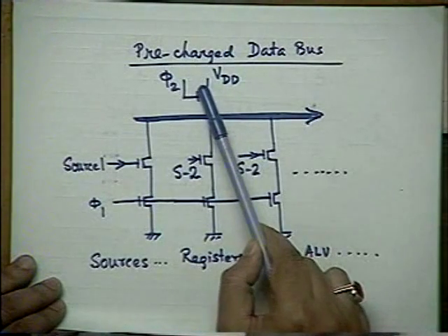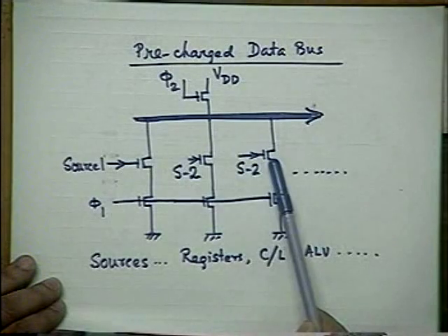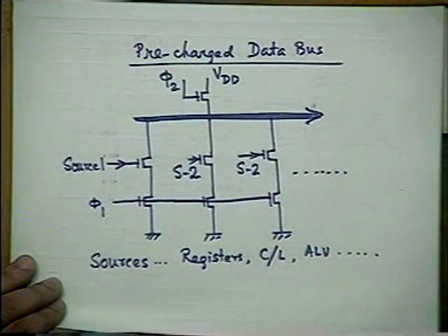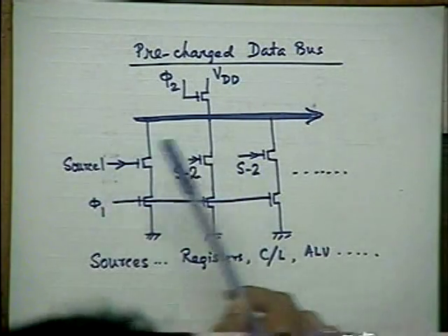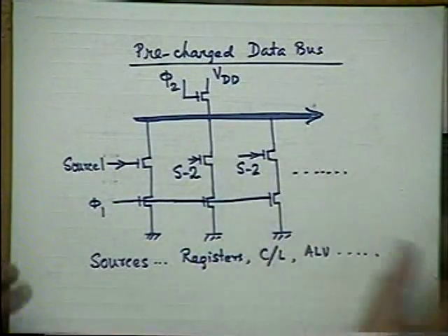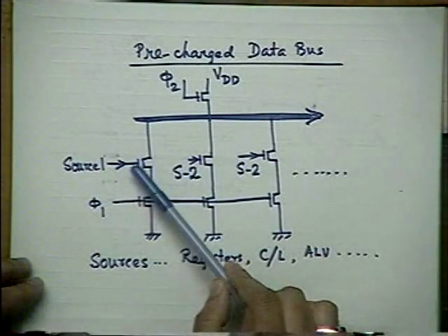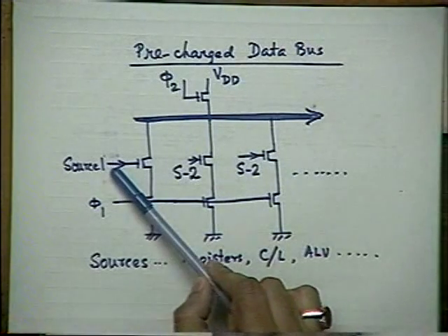During the precharge phase, the signal comes here, and you see that the output you get is fully charged. But during this time, whatever signal is coming, you are allowing time for the whole thing to settle down to a certain steady state, and these transistors ultimately get on or off depending on whatever signal is coming there.